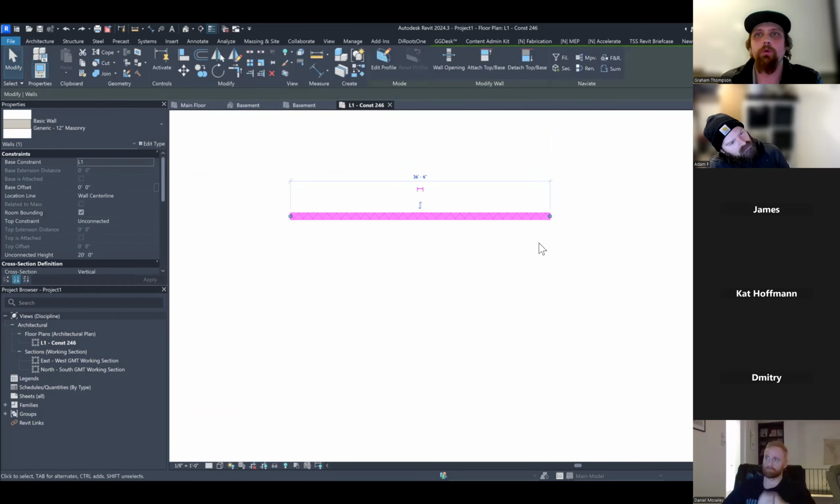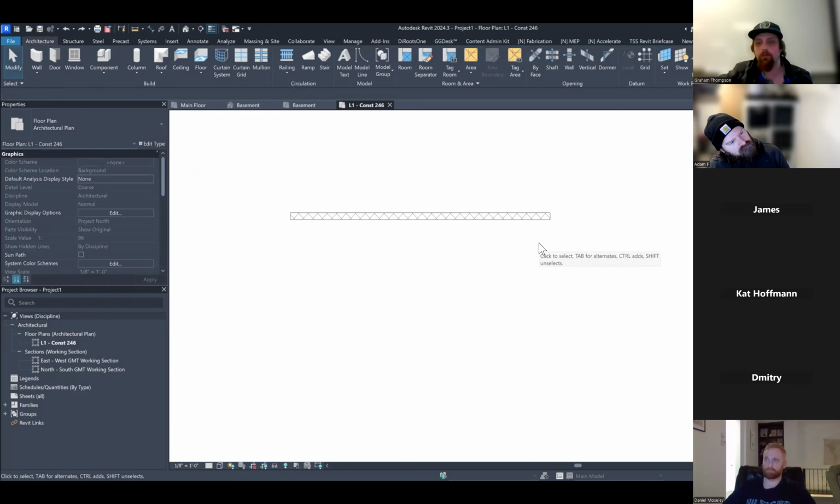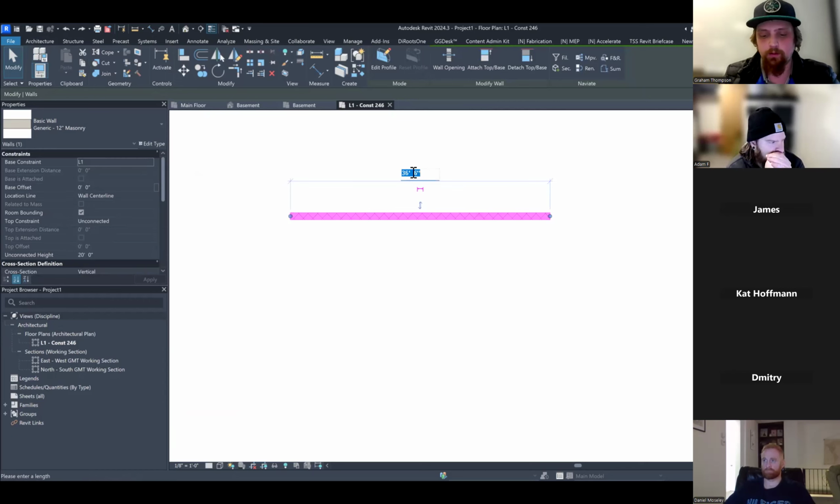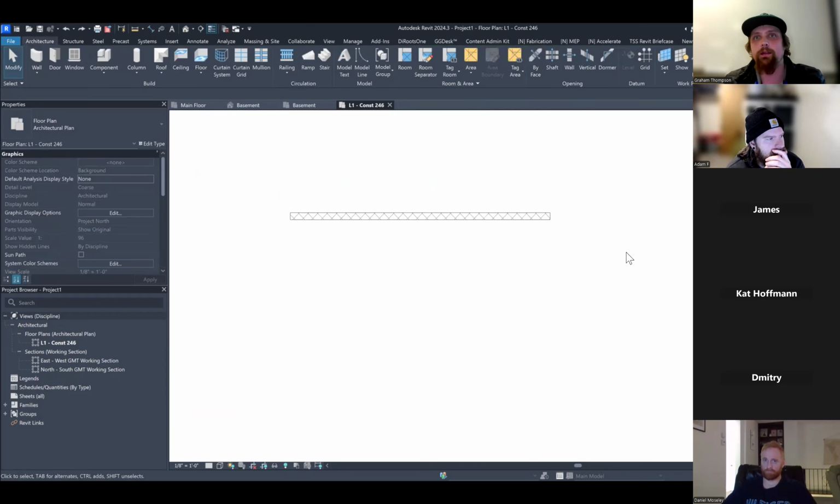We can also do other things with calculated values and equations and that kind of stuff. Revit understands all that, right? So if I wanted this to equal 40 feet plus 6 and plus 5 and 6, 5 and 9/16 inches, right? That now is that distance. It added those together, right? I gave it an equal sign in front of the two lengths and it added them together. So kind of cool. Revit will allow you to do that. Okay. Not trying to get into the weeds with that, but again, how it works is all number value based.